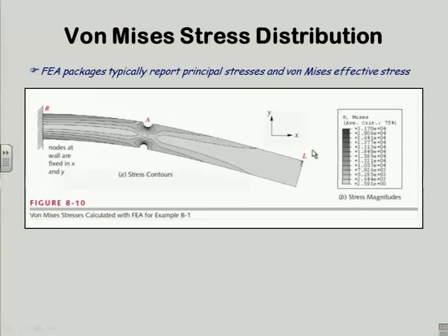Now I would ignore this from a design standpoint because I know that when I put the load on, whatever's pushing on it has some area. Okay? It's not literally a knife edge. So that's artifactual from my perspective. It's real from a mathematics perspective because I've got the load right on one point. Now these packages will let me apply the load over a length if I wish. And that might be a more realistic thing to do here. But I put it right on one node.